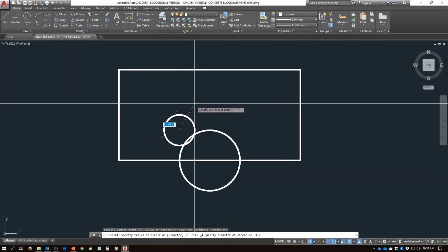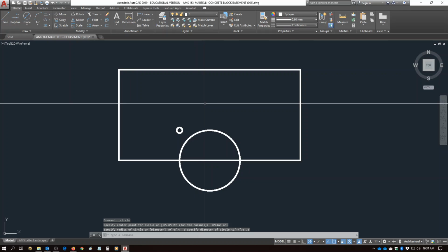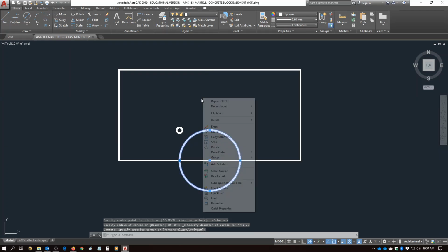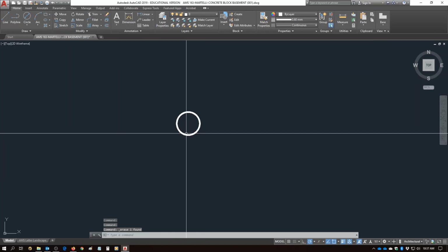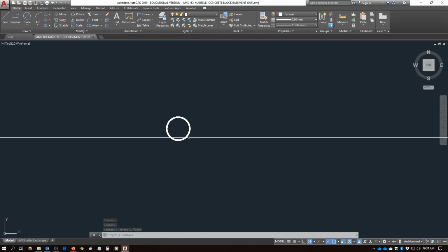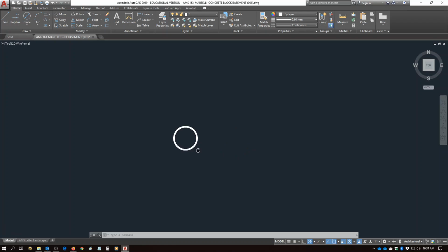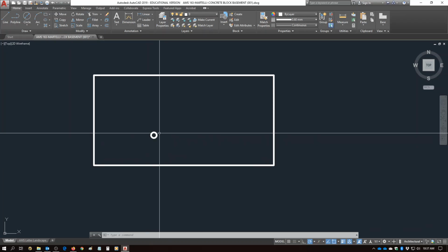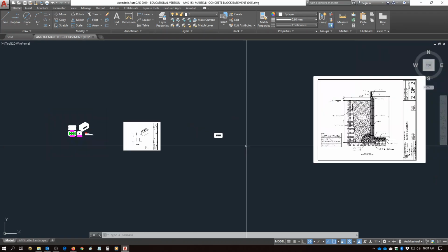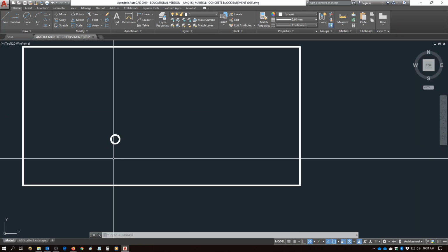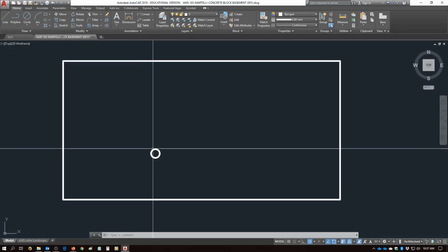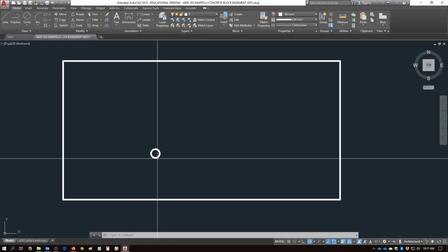Now the diameter of this rebar, again, is stated as 0.5. So I type in 0.5. Next, I can actually select my circle and erase it. This rebar, being that it gets sectioned through, well, we need some type of hatch pattern. Not only that, it's a relatively small component of a relatively large assembly. So we really want to add some ink when it prints. We really want to make sure that it's clear to the reader.